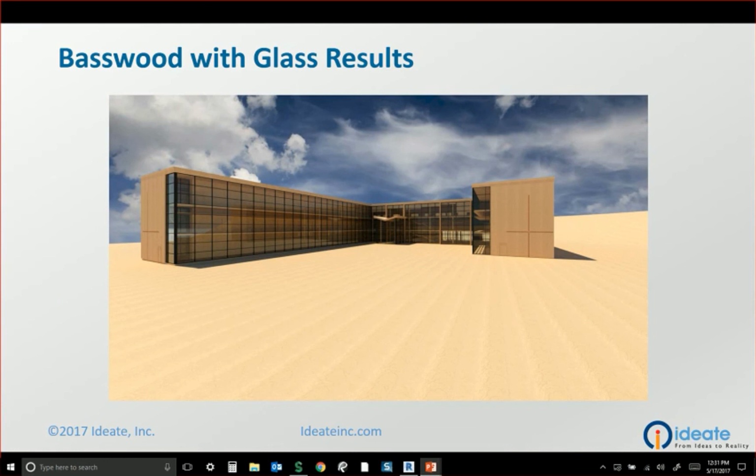So again, you want to be careful with that because you will screw up the documentation model, you'll screw up the scheduling. You can see where it can get kind of ugly, right? And this is also a good opportunity if you want to make your models render faster and streamlined, you can clean out all that extra stuff. You don't need your title blocks, you don't need your schedules anymore, you just need the model. But does that help clarify that?